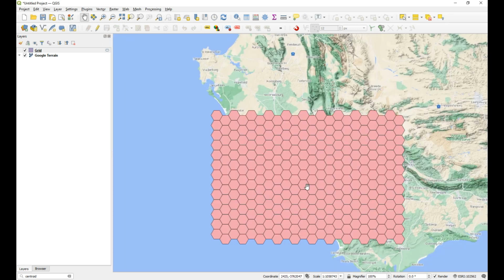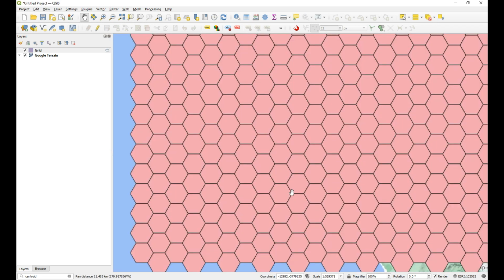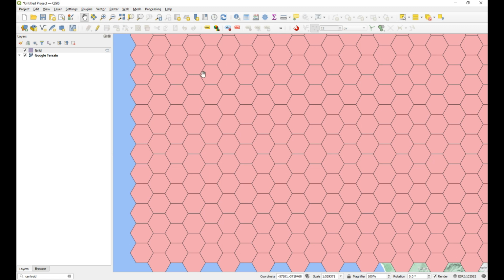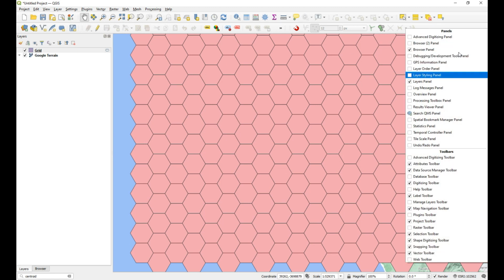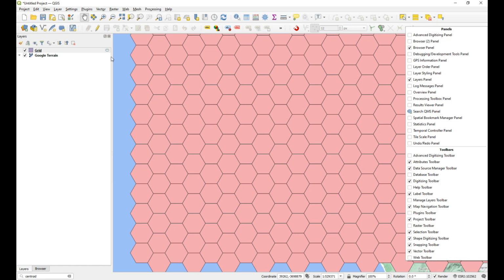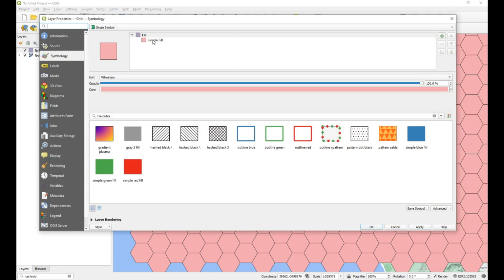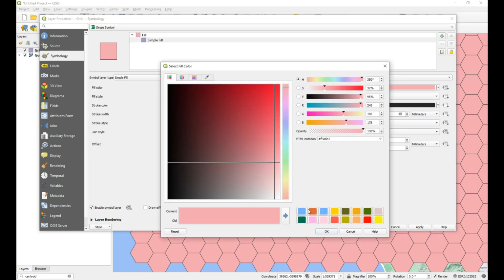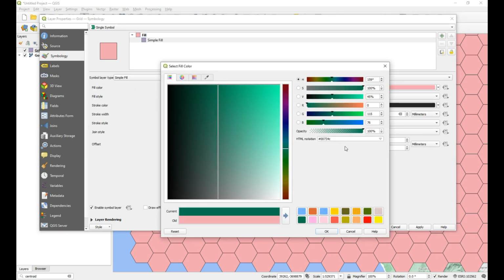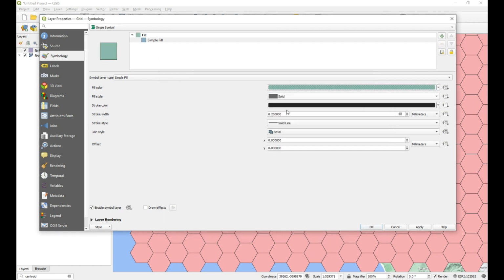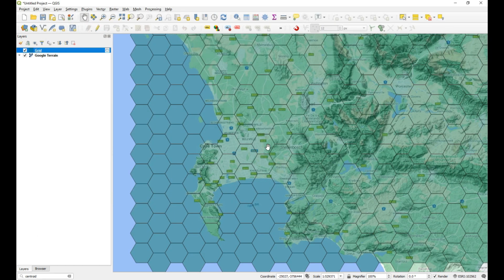Okay, there we go. So now we've got our hexagonal grid, and let's just color this up slightly differently so we can see what's happening. So I just right click on my toolbar up here. Actually what you can also do is just double click on the icon, and that's probably a simpler way, and we'll choose some nice green, and then I'll make it slightly transparent, so I'll change the opacity of the color. Now by changing the opacity of the color here, it changes the opacity of the polygon color, it doesn't change the line color. So that's why I like that option. And there we go.